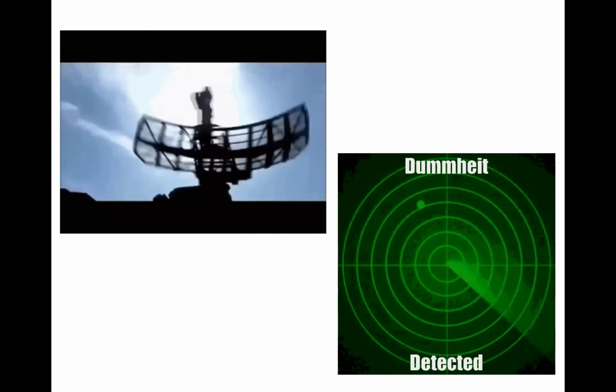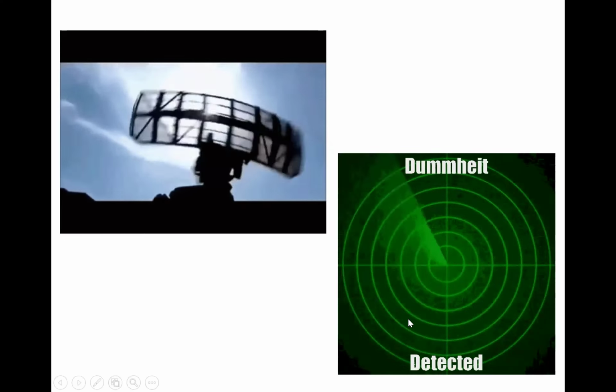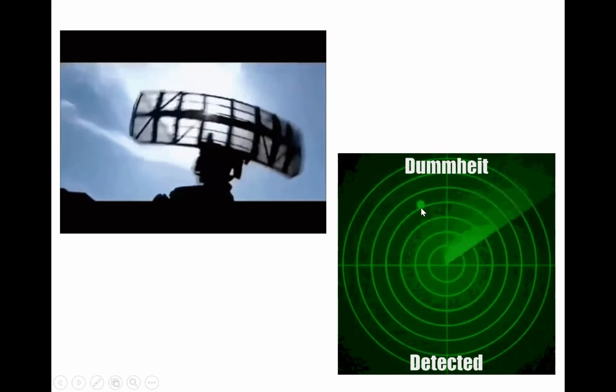Here we have different types of displays. One is PPI, another is A scope, and there are several displays, A scope, B scope, etc. But here we are discussing the PPI display unit, the plan position indicator display. Just as the antenna rotates in the outdoor unit, similarly it rotates in the display. Whenever a target is found, when the radar antenna is nearing the target, it is shown very dark.